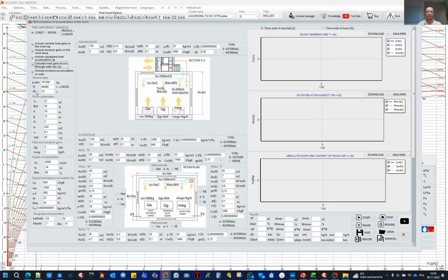So, I don't know, a conference room on a sunny summer day, standing without air conditioning, we need to prepare it within a certain time for use, so that a group of people can be let in, and we measure the time, and we study the time when the temperature stabilizes at a certain level that we expect. However, these are the simplest possible calculations, and it is known that all these heat gains or airflow, supply, and its temperature are defined as fixed input data.